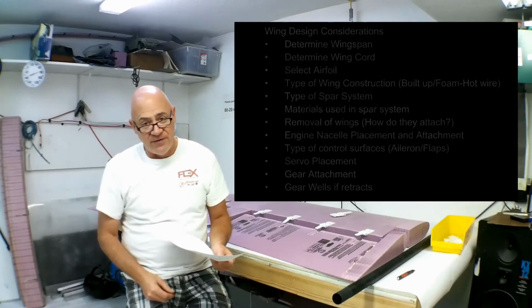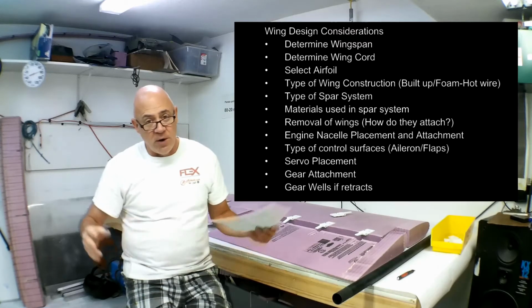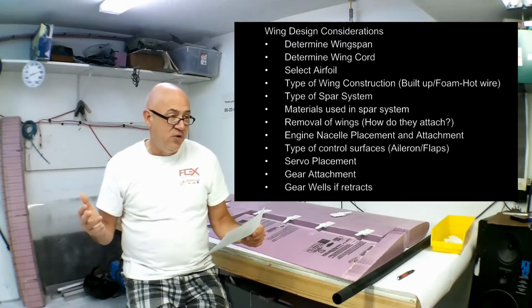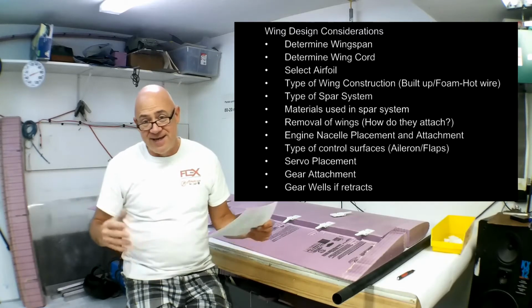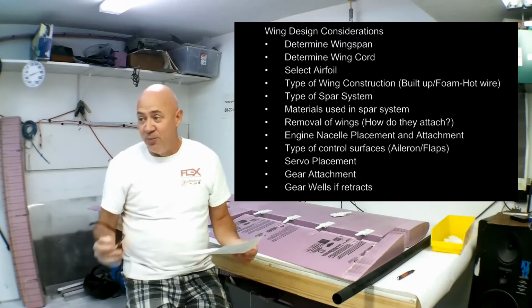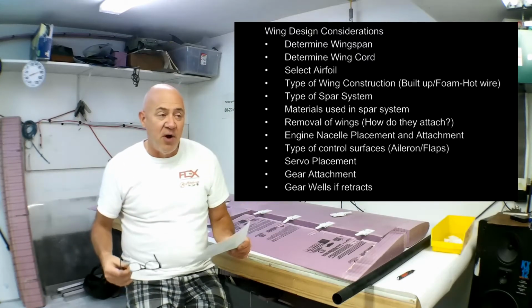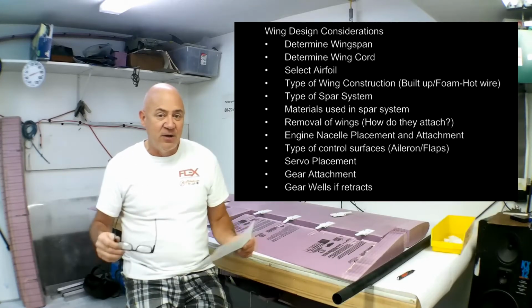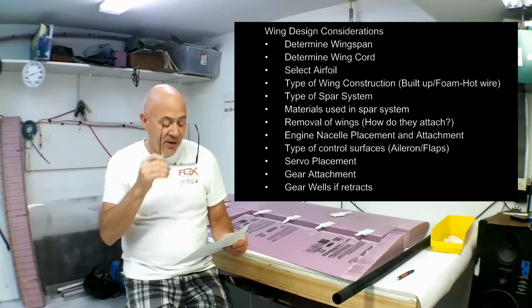So then we got to consider the wing design considerations. And the wing is probably one of the most complicated parts of the airplane, because if you do it wrong, it's a really big, heavy chunk of stuff. If you build it too light, it's not strong enough, and you land and a landing gear might go through the wing, or you pull a high G maneuver and collapse the spar. And I'm going to talk a little bit about how you understand how strong is strong enough, okay?